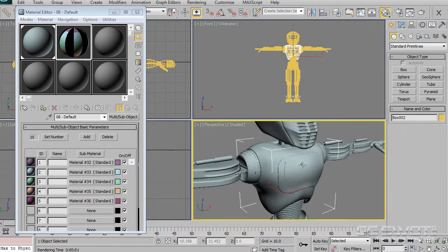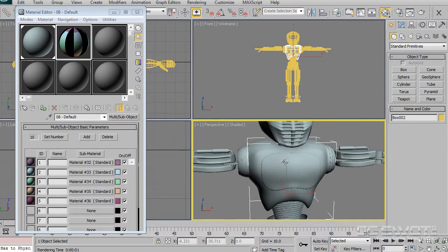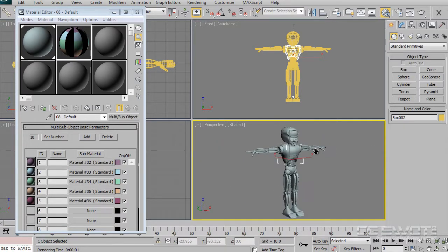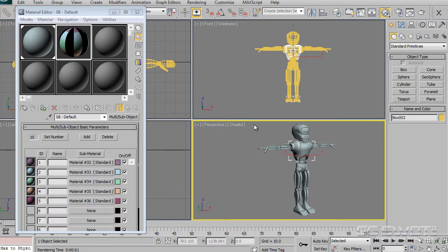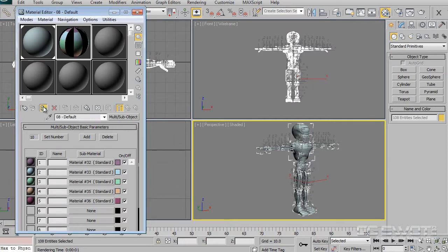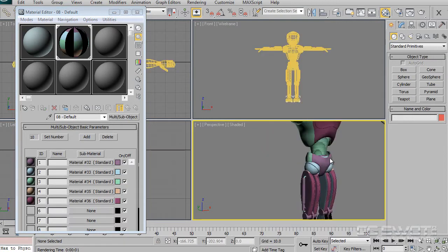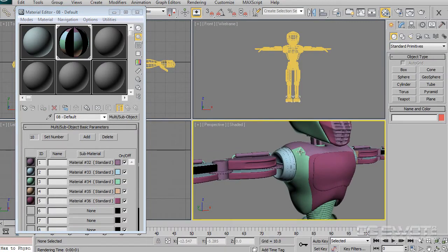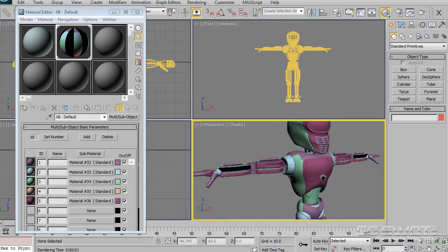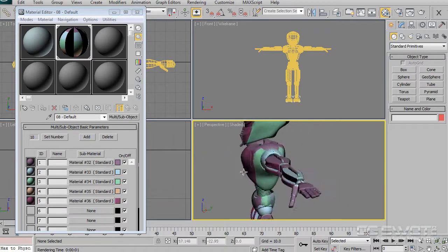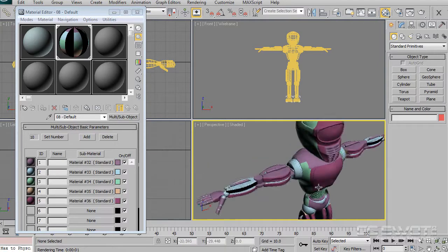So I'm starting with this torso geometry, and before we hone in on specific geometry, I'm going to select every piece of geometry in the scene and assign my material to it. That's confirmed up here with the little white corners. You'll also see that by default there are a whole lot of material IDs that have already been assigned as part of the modeling process, and that's just something that happens as you model.